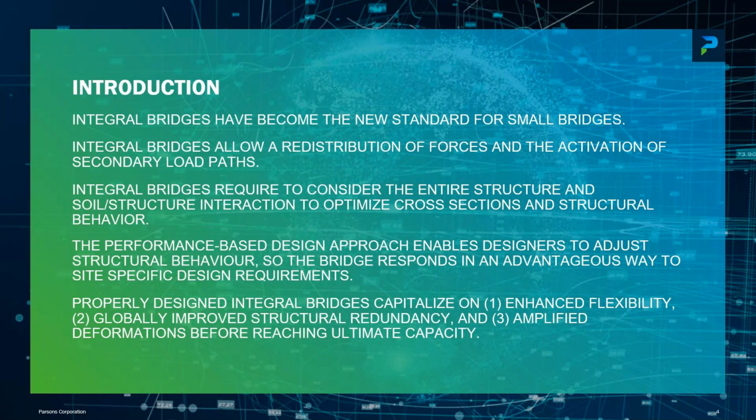Integral bridges allow a redistribution of forces and the activation of secondary load paths, and this is, from a safety philosophy, very, very important. Integral bridges require considering the entire structure and soil-structure interaction to optimize cross-section and structural behavior. The performance-based design approach enables designers to adjust structural behavior so the bridge responds in an advantageous way to site-specific design requirements. And I think this is something that is really, really important, and that's why I believe that performance-based design, that we are very familiar with in seismic design, will come as well into typical bridge design applications, because it gives you the possibility to create better structures.